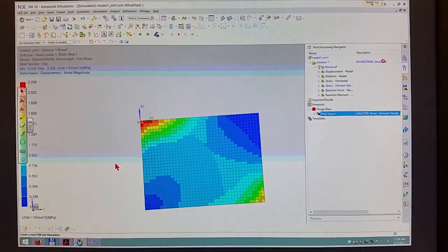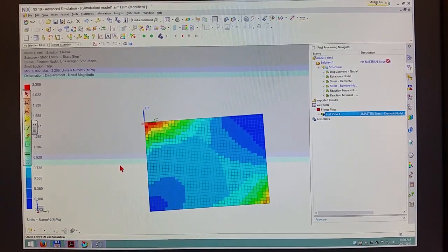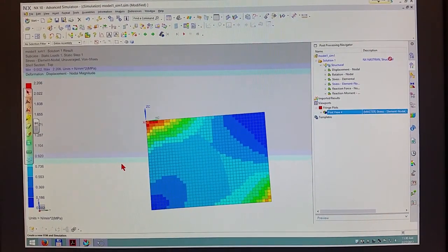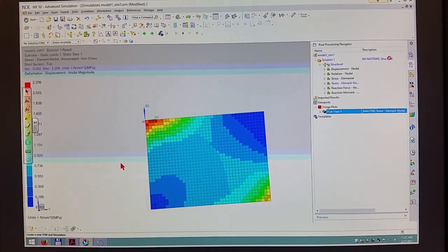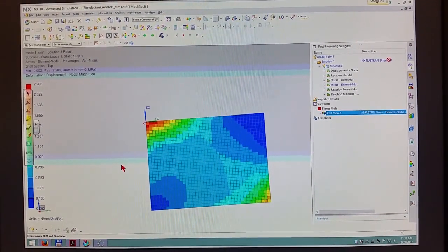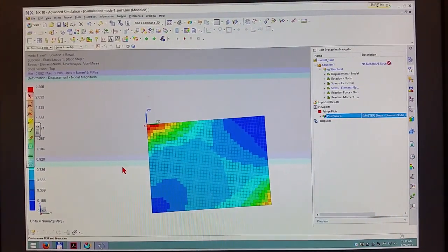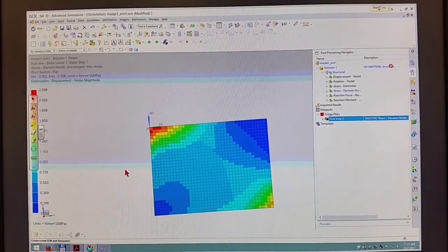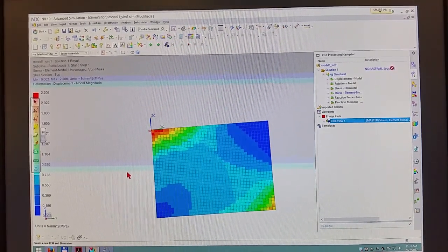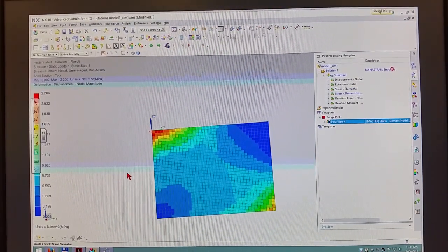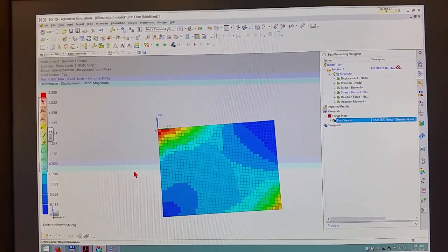So it's horizontal. At that point, that's how we define where the elastic point is, right? That's how we come up with our modulus of elasticity, it comes from that curve. It's a straight linear fit on that curve. Now, when it goes over that little hump and levels out, that's when we have plastic deformation. When we have plastic deformation, it doesn't take any more stress to displace it. Once you get to that point, you'll see a little drop.